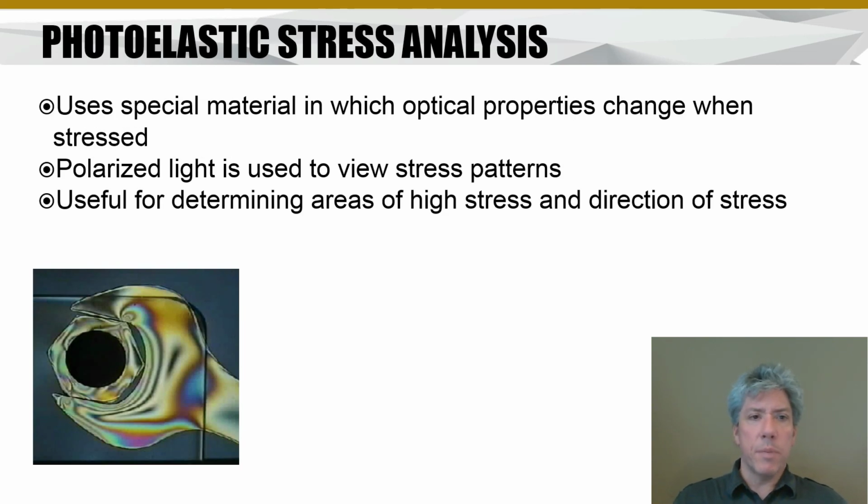Photoelastic stress analysis basically just uses materials that change optical properties when they're stressed. So you always have to use polarized light, or a polarizing filter, in order to see it, but it's really interesting. And if we were in class, we'd have some demonstrations where I use what's called a polariscope and some other things to show you what these interference patterns actually look like. That's what they really are.